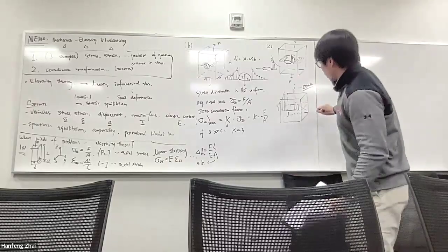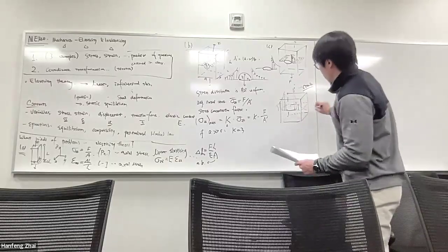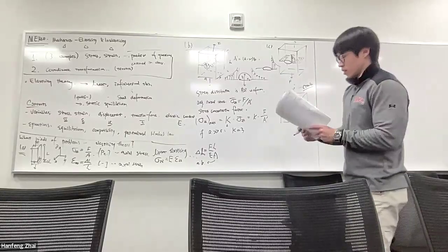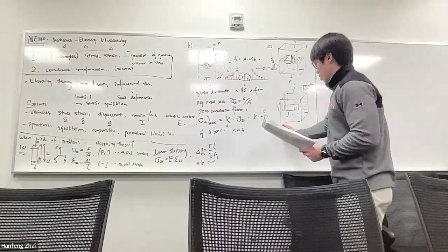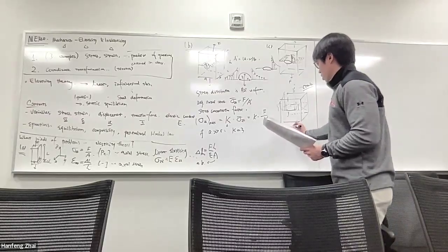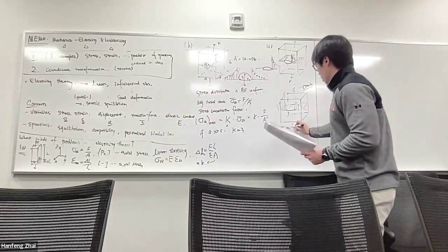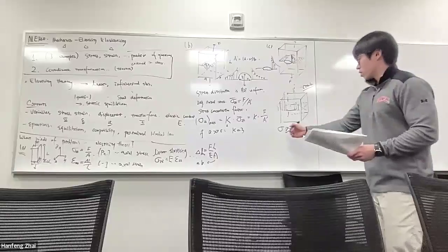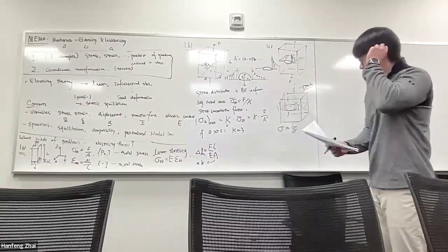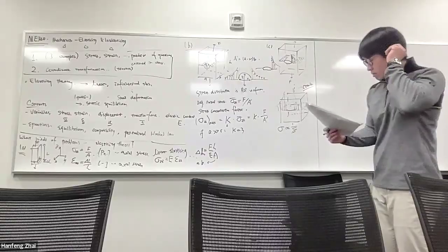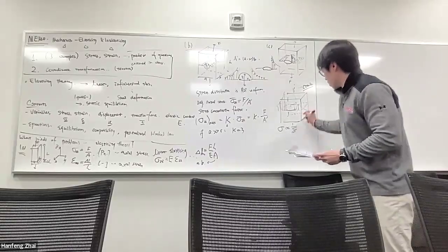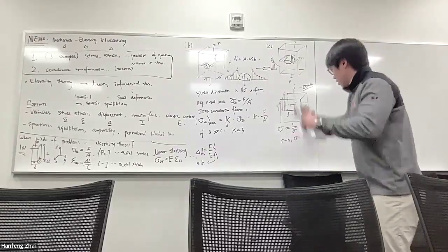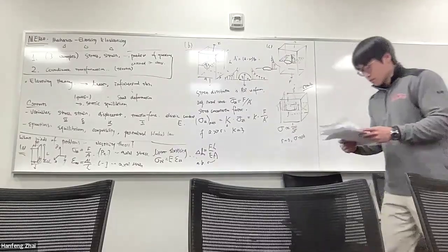And at the crack tip, what is the stress distribution? I'm just going to provide you the answer, and you will learn how to derive it much later in class. The stress distribution correlates with the radius r. It's a very important relationship. It correlates with 1 over the square root of r. And as r goes to 0, you can see the stress goes to infinity.